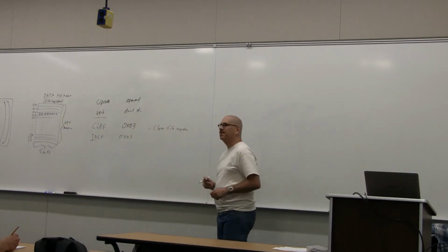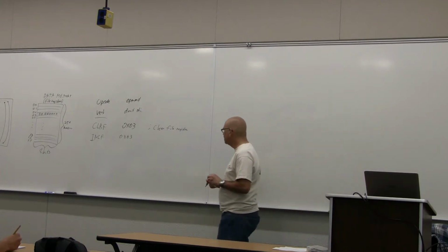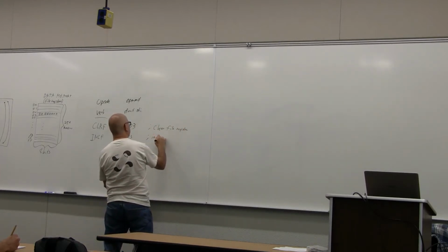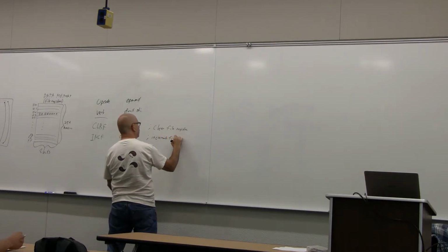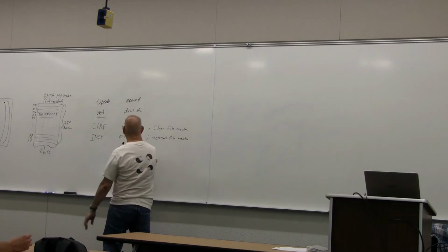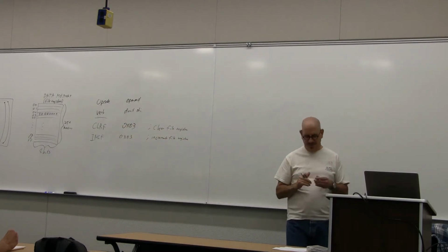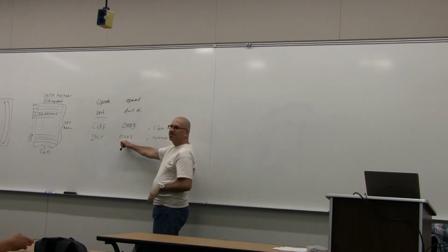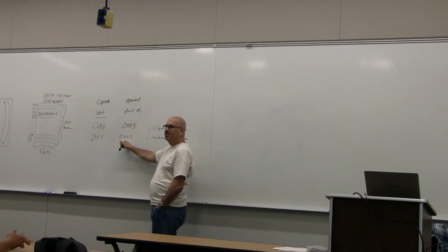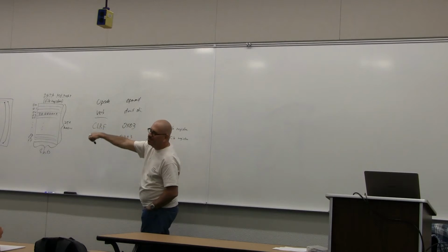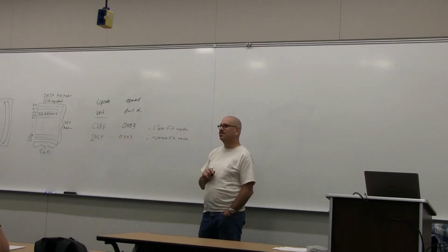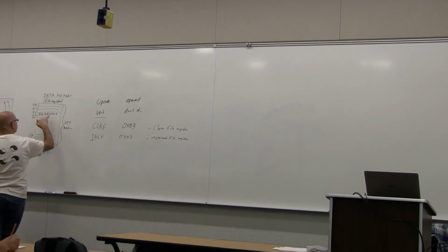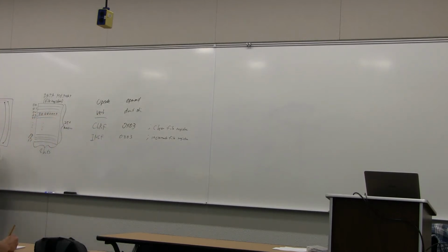Another instruction is increment file register, INCF. This is what we call a read, modify, write. To increment file register 3, it means do 3 things. 1, read what's in this file register right now. Then add 1 to that value, then write that new value back into file register 3. So this will read register 3, and we just cleared it, so it reads a 0. It adds 1 to 0 and gets a 1, and then it writes that back into file register 3. So now this is what register 3 looks like.